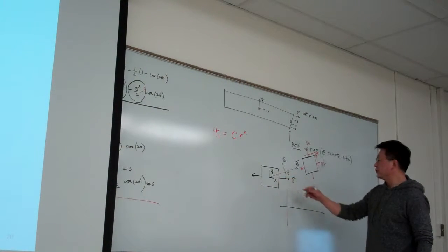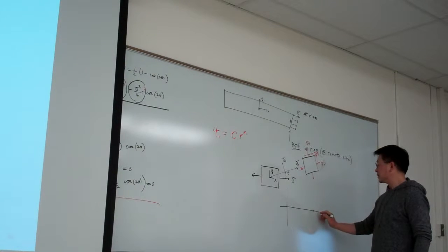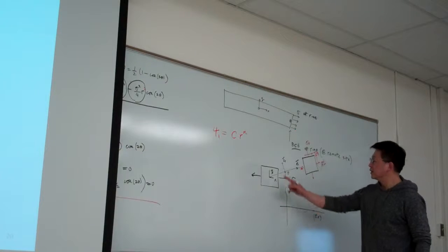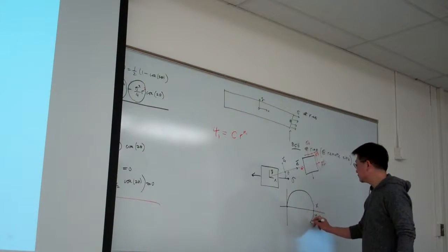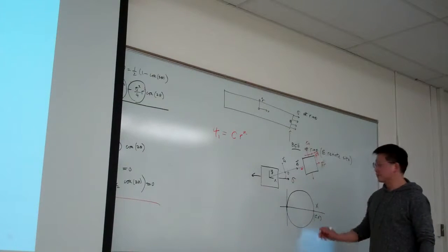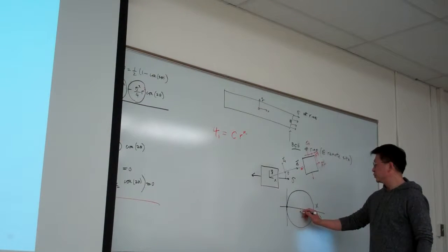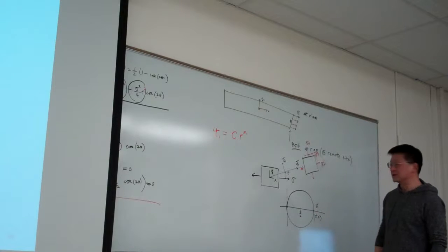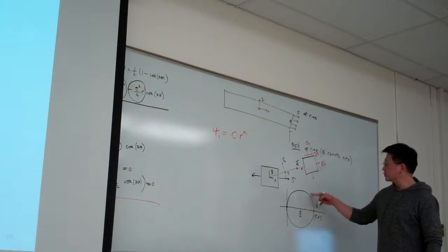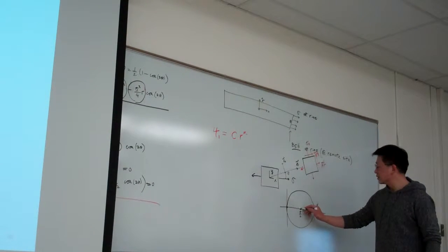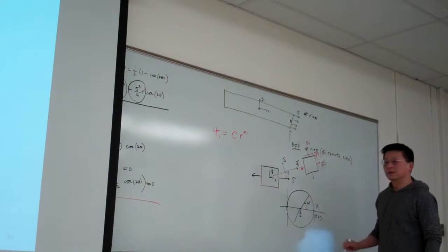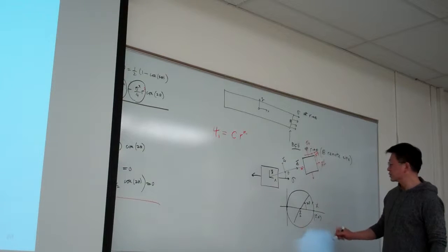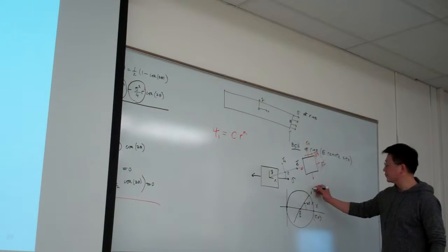In the x-plane, we have the stress sigma and zero shear stress here. This is our x-plane. In the y-plane, there's nothing here, so this is our Mohr circle, right? And the center is, per this drawing, like this. We want to rotate by theta. That means in the Mohr circle, we want to rotate by 2 theta. X, according to such rotation, moves to x prime.